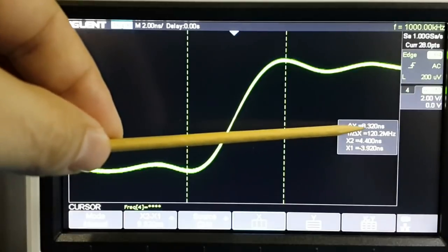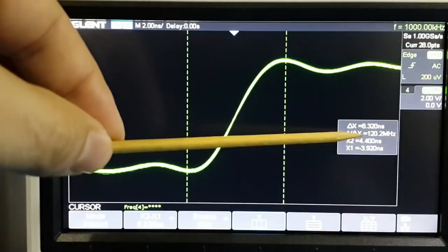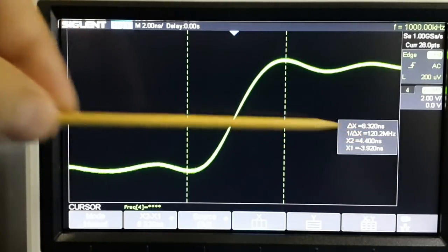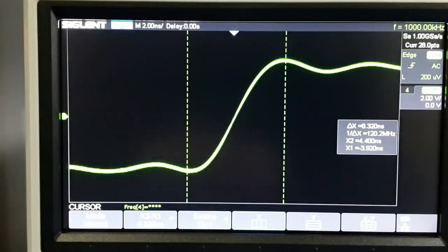Behind the scenes, controlling this, we can see the 120 megahertz, the function generator's capability, the maximum frequency. That's the reason why a function generator able to give 120 megahertz will only give a 25 megahertz square wave or 1 megahertz ramp, because it's about the 8.4 nanoseconds rising time, and that's the guy who will decide what our frequencies are going to be in our function generator.